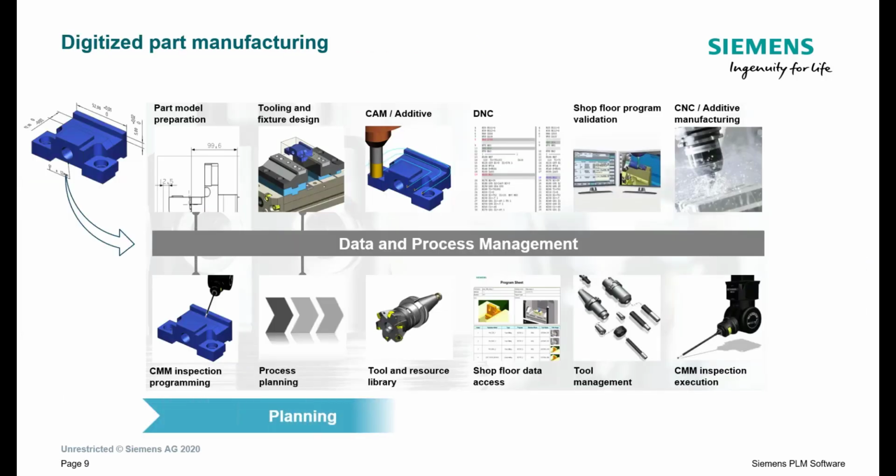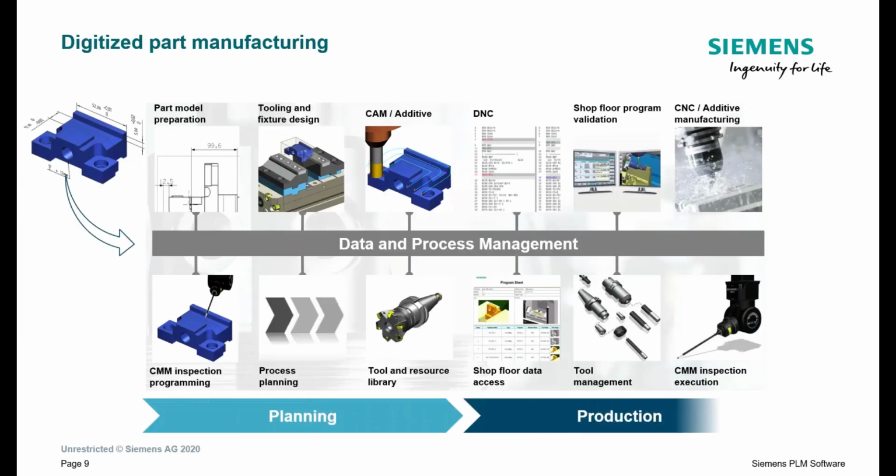The 3D solid model can be read or designed in your CAD system. The digital twin of the part model is the input to the manufacturing process. Ideally, you want to work in the same software system where you design the 3D part model and define the entire setup, including the fixture, so that we have one consistent environment. By using the same model definition, you can take the data into the CAM module for NC programming to create and validate G-code to drive the machine tools.